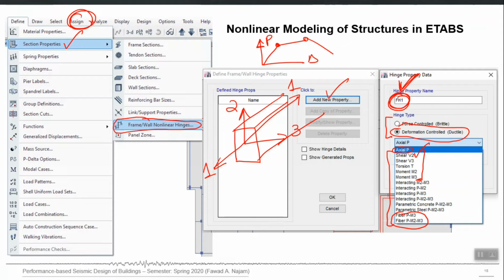So if this is a beam, let's say, with this cross section, and I apply a vertical load, the M3 will be actually the default bending moment caused by that vertical load. Let's call it some N, because if you point your thumb towards 3, the curl of your fingers will be in the direction in which this N is going to bend your beam, right?